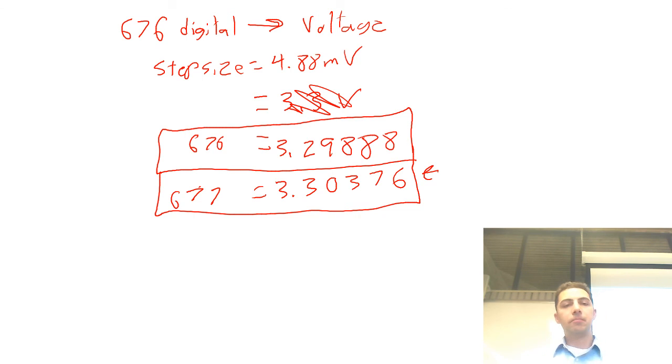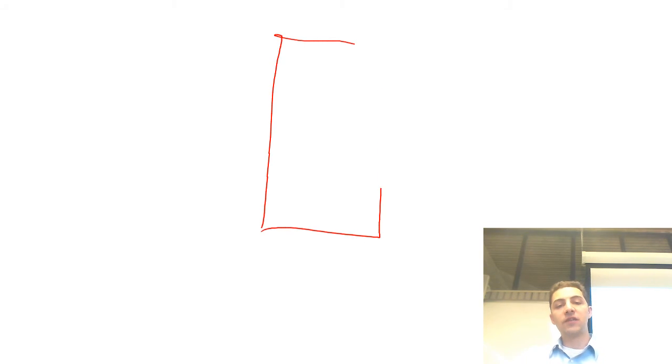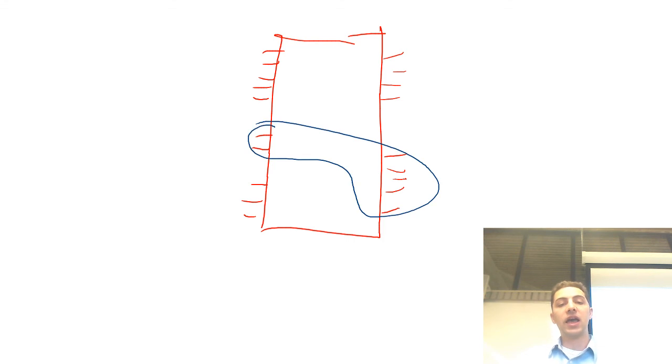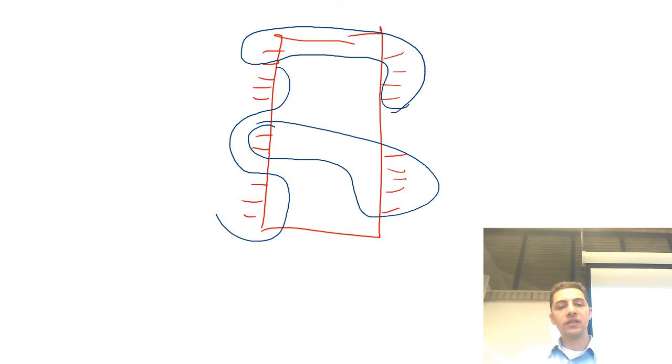Okay. Basic differences between pin change and external interrupts. First off, if you think of your processor, it's got port B, C, and D. Pin change interrupts can happen on just about any port that you want. And this is kind of roughly where those ports live. Okay, so they can happen on any of them.